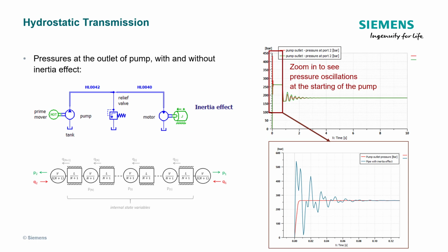Now compared to pipe submodels from previous slides, you may already notice that except for the capacitive effect, which is considered in the circles, and the resistive effect, which is considered as the shaded area, there are rectangles inside the shaded area. These rectangles are equivalent to fluid inertia, and usually for a long and thin pipe, you could consider it in several sections for more accurate calculation.